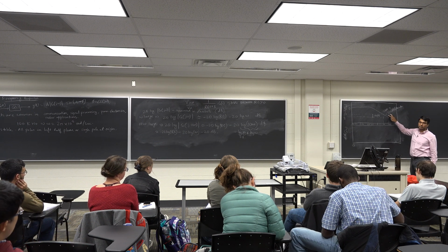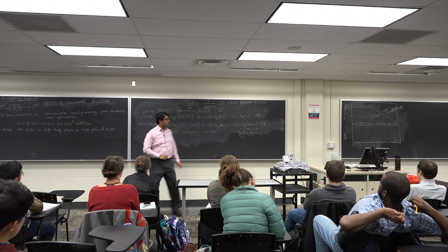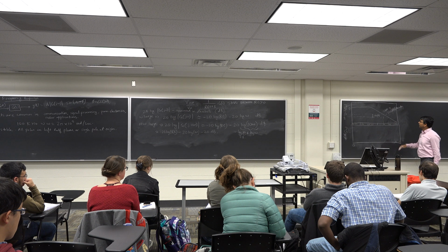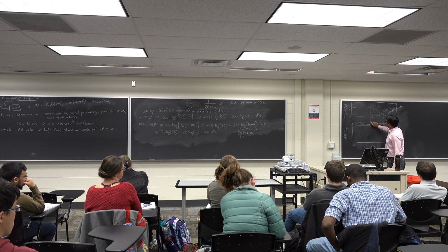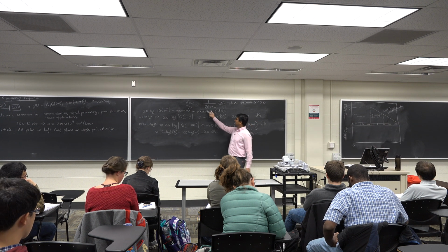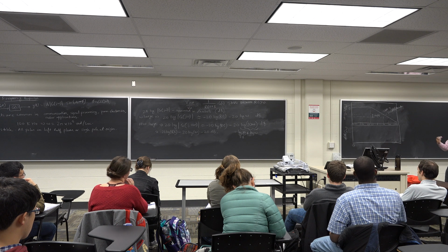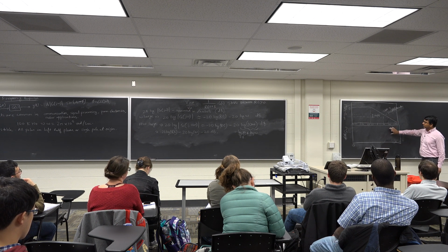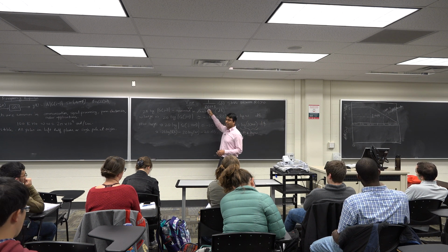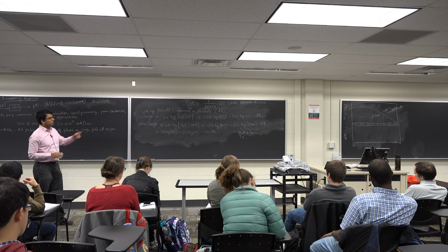If you notice that the slope is minus 20 dB per decade, what does that imply? It's a system of this type. So in those days, being able to plot the Bode plot was very easy because you had the hardware tools available to plot it. And by looking at the slope, and at this point where the slope changes, from 0 to minus 20 dB per decade, you can actually identify what the value of R multiplied by C is for that particular system. And that's why this plot became extremely useful at that point of time, because it was easy to plot this graph for a specific system. And using that graph, if you have enough experience, you can identify what kind of system transfer function you are looking at. We will get to it in a bit, but I wanted to show you that this can be done here.